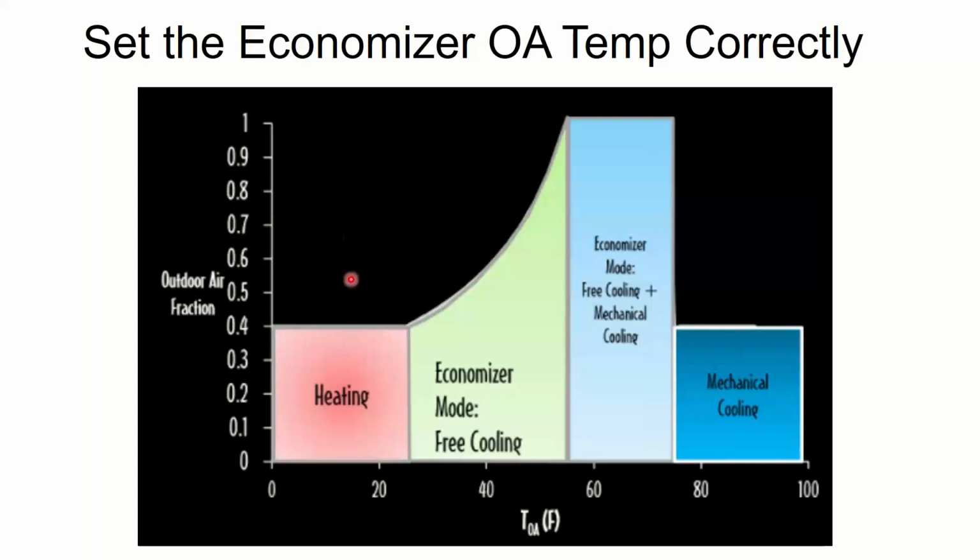And in heating mode, what that would mean for me is, A, I'm spending a lot of energy to heat all that outside air. And I think everybody knew that was going to happen, and they were okay with that. Like, hey, let's waste some energy, if you will, in order to keep people safe while we figure out what the hell is going on. All right, that's fine. If I'm in mechanical cooling mode and I do that, though, it gets kind of detrimental on the dehumidification side, which I'll show you in a second.